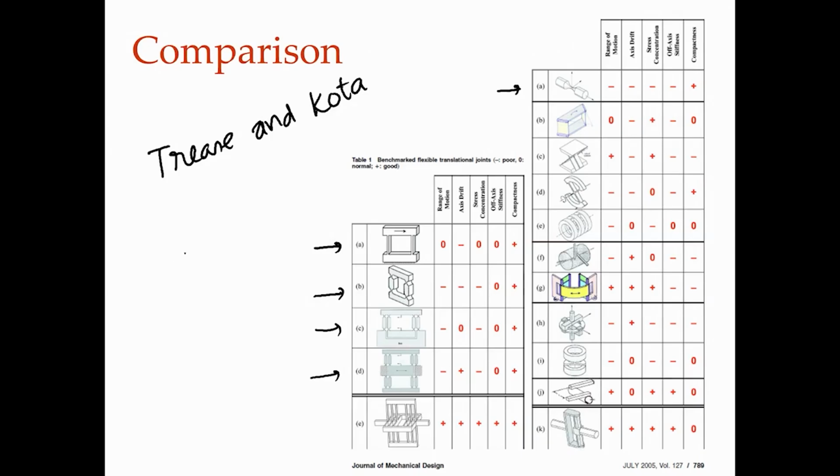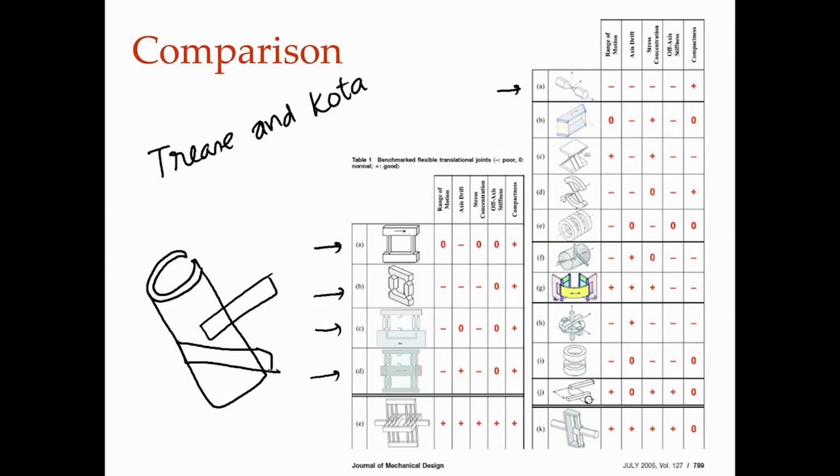If you take a tube, okay, let us say we take a tube and have a little split on it somewhere here, then if you attach at one end and then the other end, okay, tangentially at 90 degrees apart, between these two you can rotate, and that gives you a very nice flexure equivalent. It is called split tube flexure. There are a number of other configurations actually.